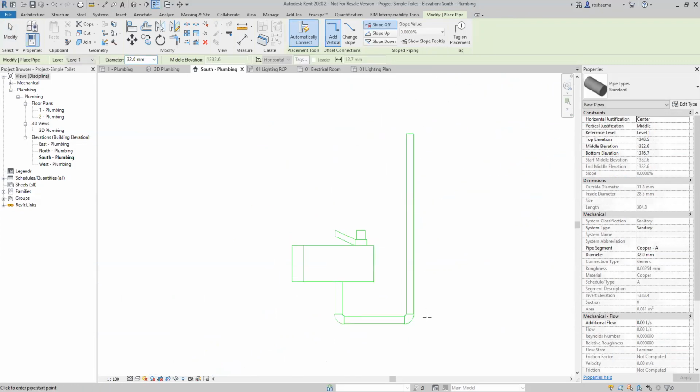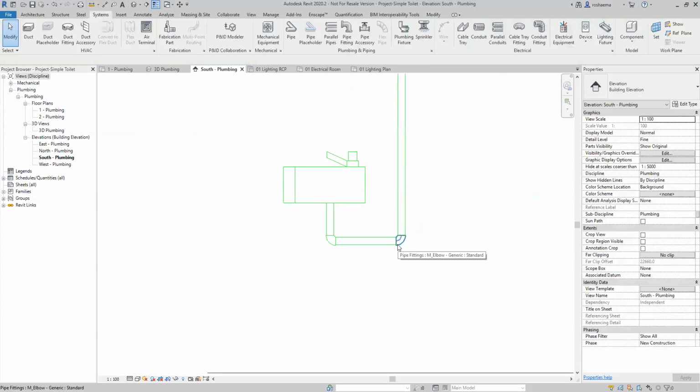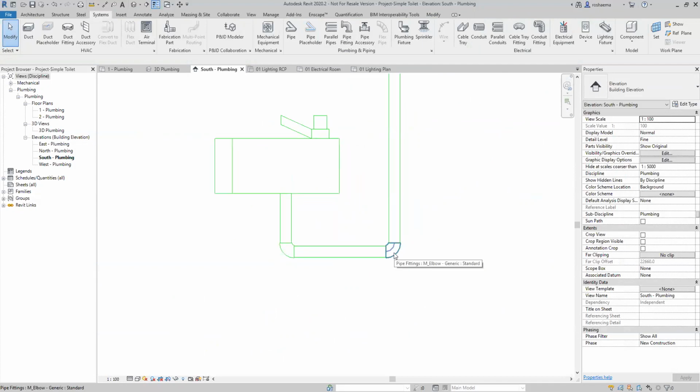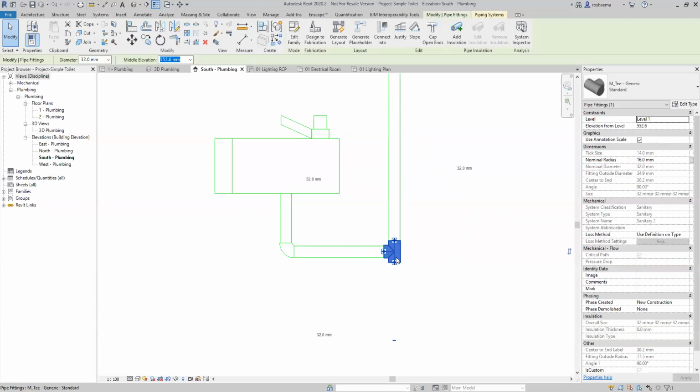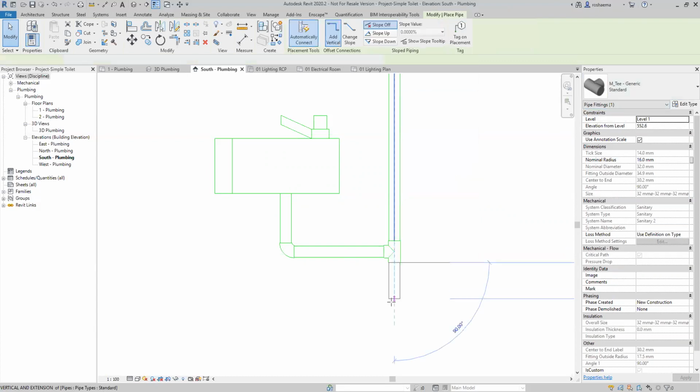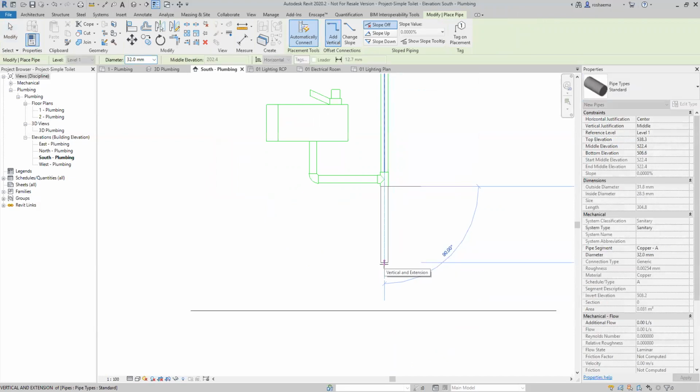Okay, let's say you want to modify or add a direction, you can just click at the elbow. You can actually change right from here. Okay, you can see that there is a plus sign here. If I click that one, it will change the elbow to be a T elbow. So you can just draw pipe again and then to below.